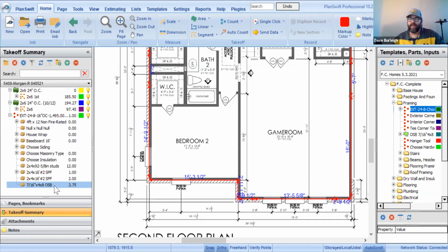We want to set out each wall as its own independent wall so that it has its own independent material list that goes with that wall. Once we finish doing that with the walls themselves, now we're going to go look at our corners also. We've identified that corners are an area that unfortunately just kind of get fudged when they're being estimated, and they shouldn't be. We know what all those corner details are. You as a builder should know which corner details you're using in your homes. So now we know what's the actual stud count that we need to achieve a corner.